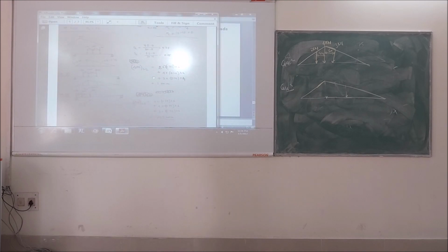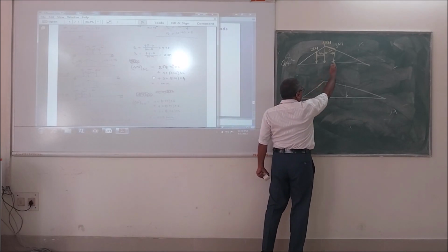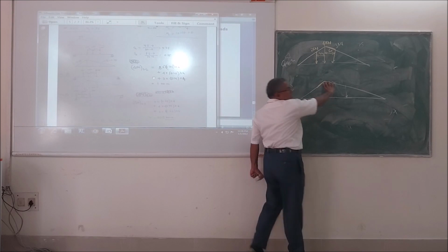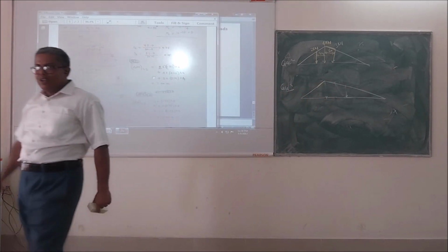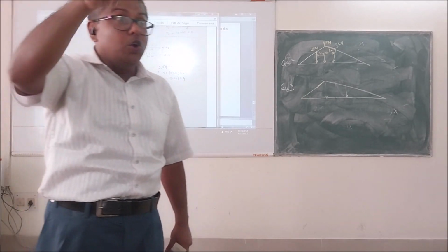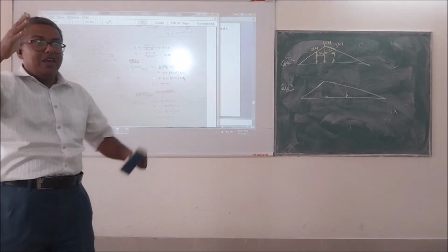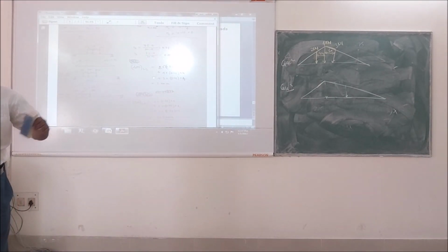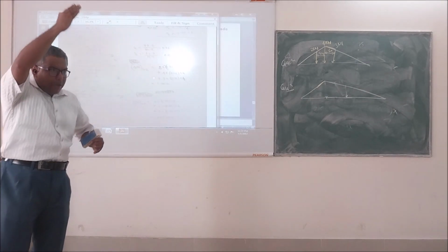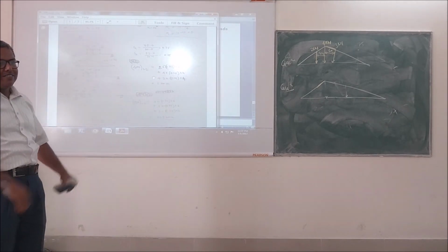Correct. So you see, it is not 4 meter. Why? Because if this 3 kilonewton load now moves by 6 meter distance, this much distance, then only it will be positioned at the maximum ordinate. So movement depends on the load. And how do you place the load on the maximum ordinate? That is very important. So if my back load is moving by 6 meter distance to be positioned over the maximum ordinate, then how much will be the movement of the front load?